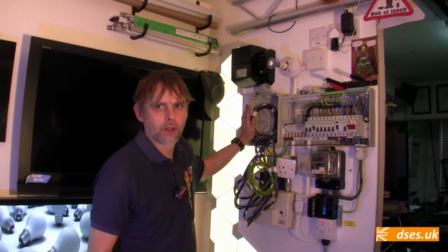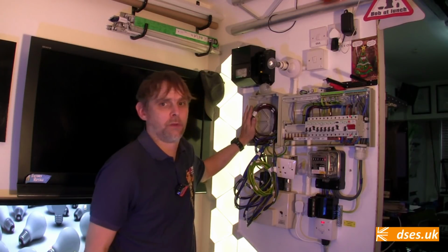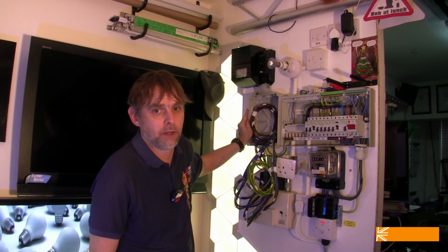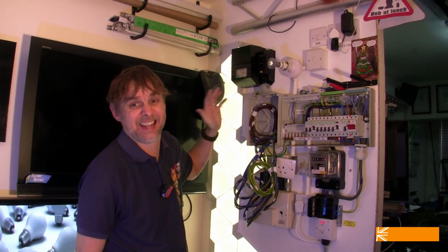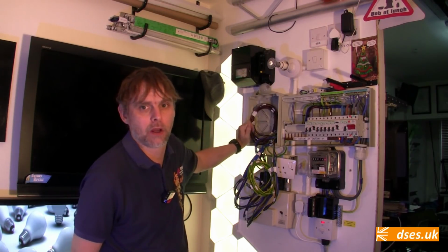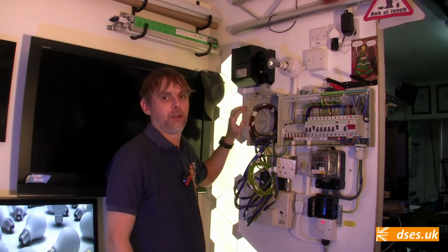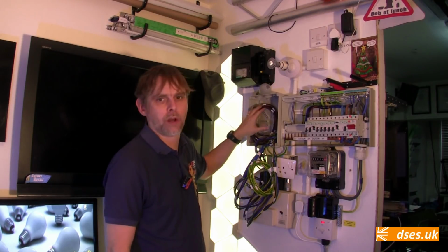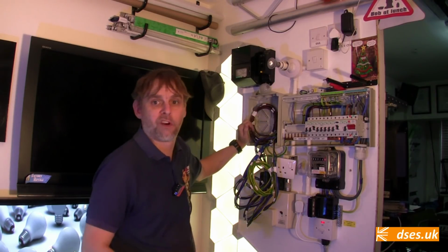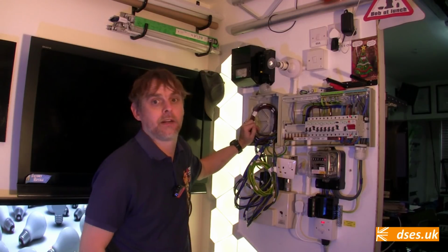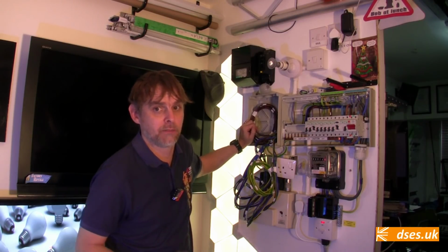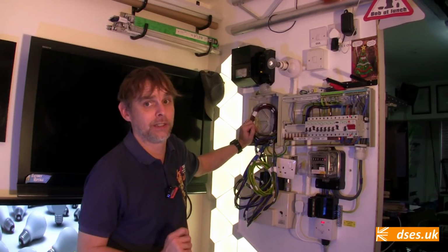Jolly good. All very well, and my apologies for blabbing on to all those who just want me to get to the point. And indeed, what has any of this to do with our nuisance glow, you may well ask? Well, I've demonstrated that my 2.5mm socket wire forms one half of a capacitor. My 1.5mm lighting wire running alongside it naturally forms the other half of a capacitor in much the same way as my non-contact voltage indicator did.